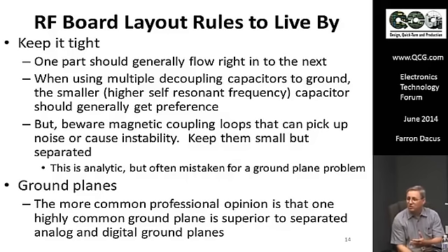So there are occasions when in this layout you would use other segments of ground plane, though in general the practice is you're going to set up one ground plane everywhere, including your digital section, though you're going to distance that off from an RF section. That is going to be set up for 50 ohm microstrip.